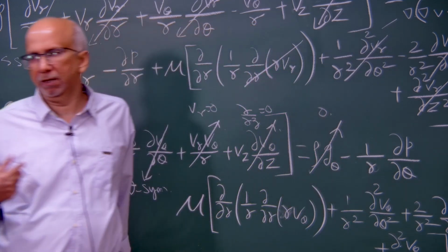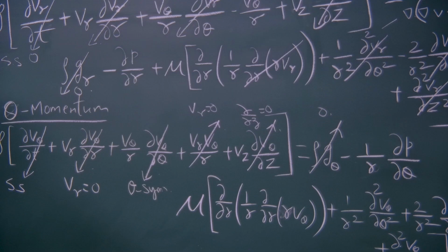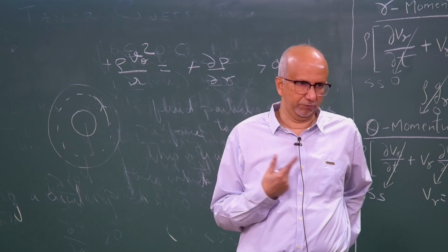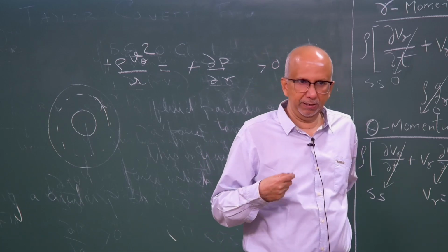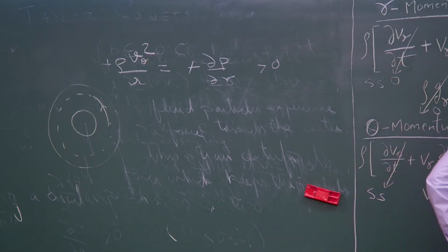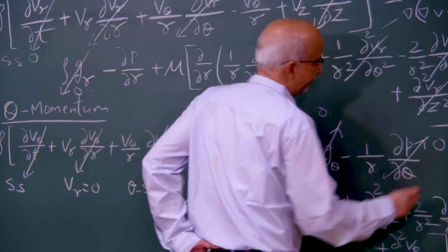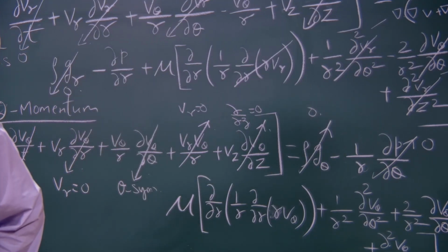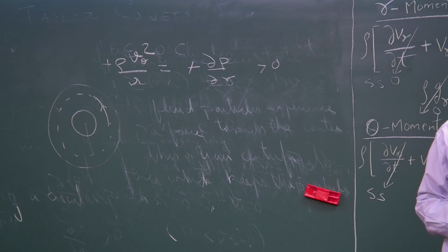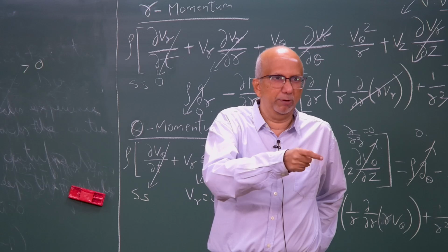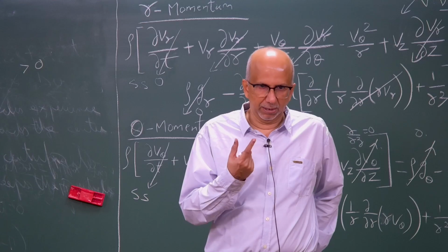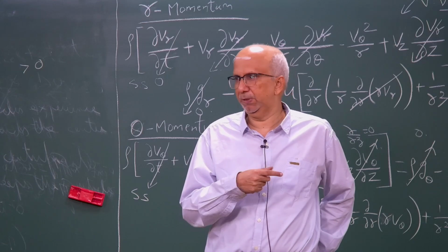I am not imposing any pressure gradient. Like in the Couette flow problem of Cartesian coordinates, the wall was the one which was giving the flow. So again here I am not imposing a pressure gradient, and therefore I am saying this is 0. Again same funda, you will have to have pressure if you go in the theta direction. If dp by d theta is positive, pressure will keep on increasing, and at the same point you will have two different values of pressure. So, the only way you can avoid this kind of contradiction is if dp by d theta is 0.